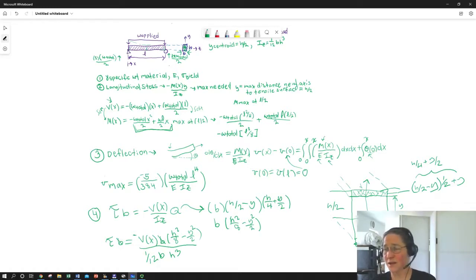In some cases of shear, we do or don't have a dependence on b, depending on the shape. We definitely retain it here. So it's less consequential than height, but widening the beam is going to give us a little bit of advantage in reducing the shear. So y is basically the same as in longitudinal. It's our distance from the cross-sectional centroid, where the neutral axis is, even though the neutral axis is not as important for shear. It isn't really consequential.